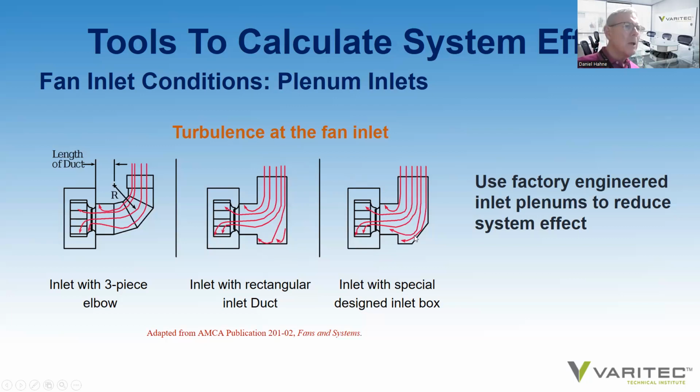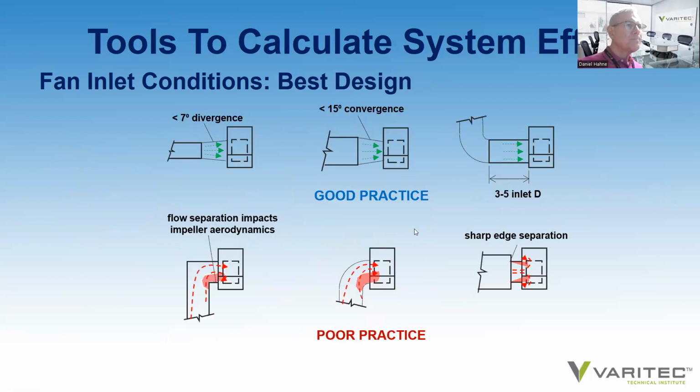I would recommend working with factories to build those for you as opposed to a contractor building it in the field who really doesn't have the resources to draw from and know how to actually design the appropriate inlet condition to reduce system effect.